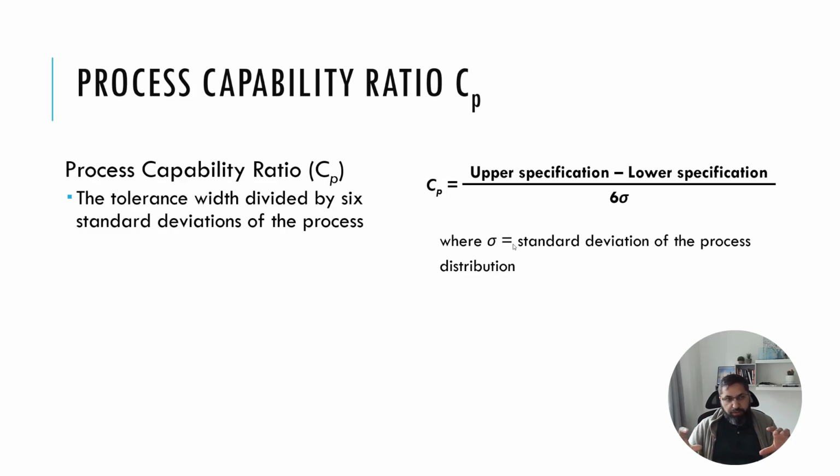And so when everything is perfect, we run the process and we measure the output and we measure the variation in the output using some exact measurement. And then we can get the standard deviation of the output, and that's sigma. So in our ideal conditions, what variability is in the output? That's sigma, the standard deviation. So it's obviously based on some measure. If the volume or the mass of the final product is important, we're filling product into bags, we can measure the mass and get sigma.